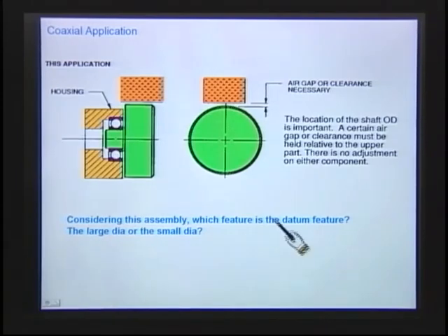In this one here, it looks like some kind of a counter or something. It looks like I have a housing, I have a bearing. I take this little green part, I put it inside the housing. It's located on the bearing. And this here is some type of a wheel. It reminds me of kind of like the anti-lock brakes. You know how I have the anti-lock brakes? I have a sensor up here, and I'm looking how close that wheel gets to the sensor. And you know how that's supposed to work is that if one of the wheels locks up and stops turning, the sensor senses that and then relaxes the pressure on that brake.